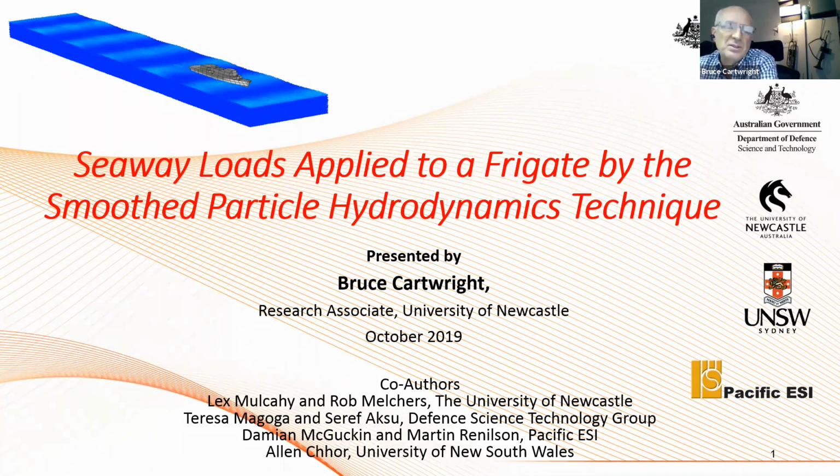So rather than run some statistical wave group and just wait and run it for long enough that you get your impact event, I much prefer the idea of a design wave train, such that you can run exactly that same wave train and get that same impact at a known time, at a known location in the tank. And that presents a much more reliable way to do a what-if analysis. If you want to vary the structure of the boat, okay, this sort of reinforcement or whatever, the stress has only got to this. What if we did this, or what if we did something else? I just see a design wave as being a much more useful tool for a repeatable situation.